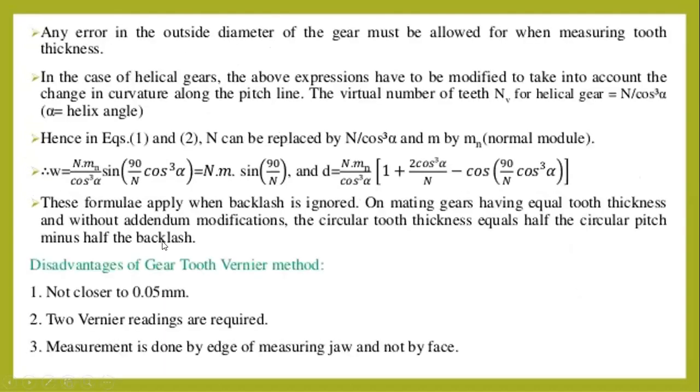So this is the final curve, and any error in the outside diameter of the gear must be allowed for when measuring the tooth thickness.